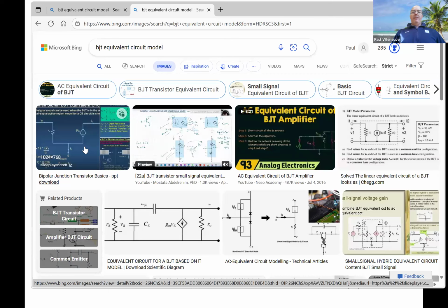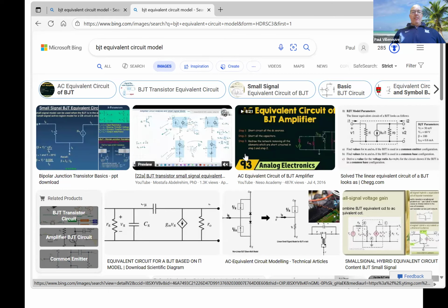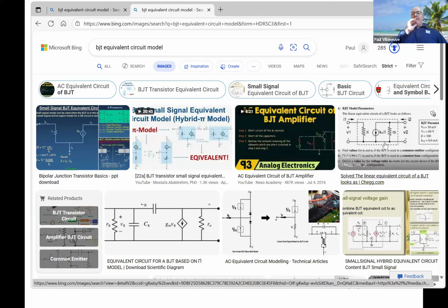Right here, this is somebody's notes. Over here, they use a different representation. They use a circle with a K multiplier. Normally, you would use the diamond symbol to represent dependent sources. So if anybody has not seen dependent sources, I just needed to jar your memory. If you haven't, that's okay. We'll do the circuit analysis necessary, but you have to do dependent sources primarily for electronic devices. Got to do those a lot.